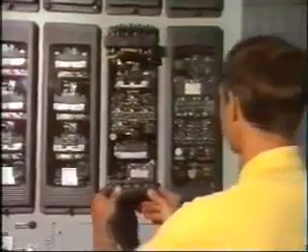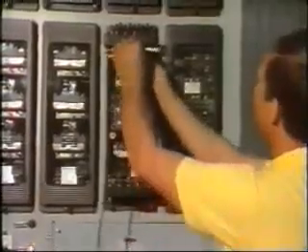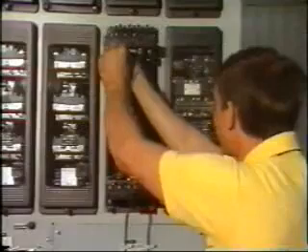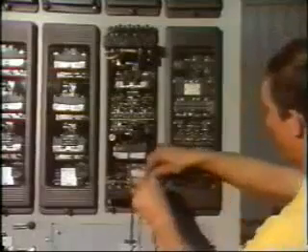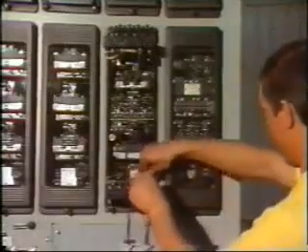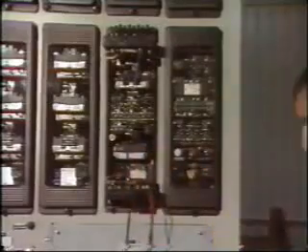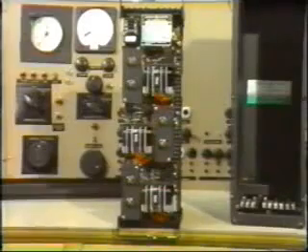We already know from earlier tapes that sensing information is provided to the protection system by coupling the relay to the load circuit through instrument transformers. Current transformers, CTs, and voltage transformers, VTs, step down the power system current and voltage to safe working levels. This provides significant protection to the relay and also to personnel working on the protection equipment. Low voltage and current also permit the relay equipment to be made small and precise.